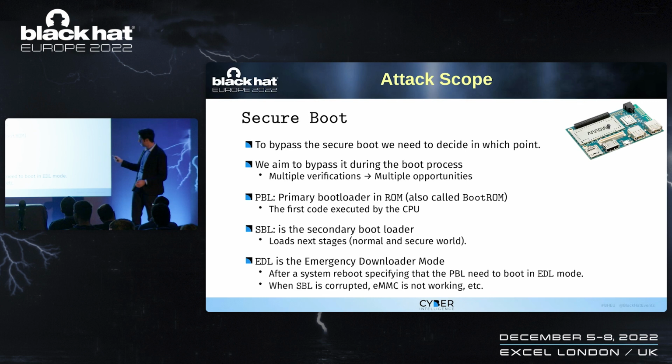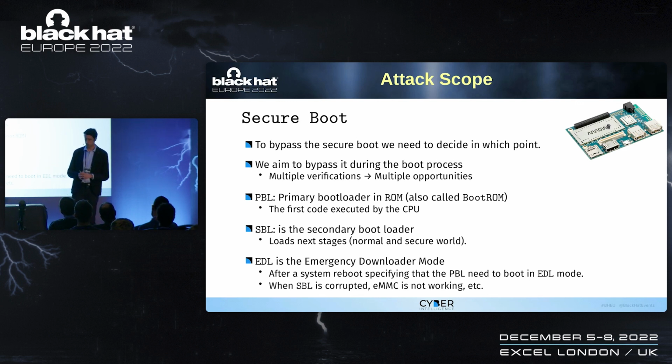But there is an important mode, which is EDL, the emergency download mode. Let's suppose that you are trying to repair your smartphone and then you remove the flash, the eMMC or UFS. What will happen in that case? Or probably you have seen a lot of people trying to reflash devices when the smartphone doesn't even boot, right? So the idea is there is an emergency mode so that in case your flash or your flash partitions are super damaged or whatever, you can always have some communication with the device. This is the emergency download mode. I'll explain in a minute.